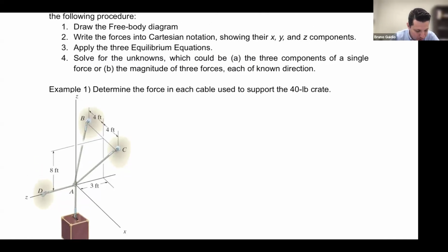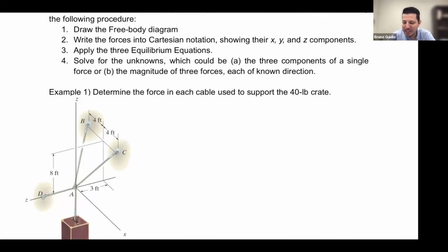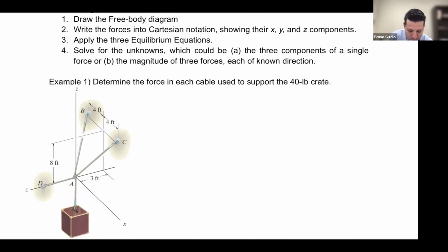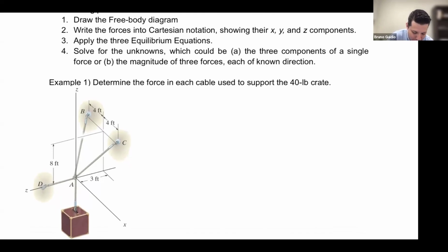Let's start with the first step. What is the first step? Draw the free body diagram. Let's understand the problem. We want to find the force in each cable. Where are the cables? I have cable AB, cable AC, and cable AD. I have force tension on those cables, tension being applied on this point A particle.